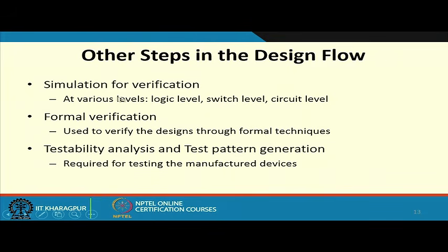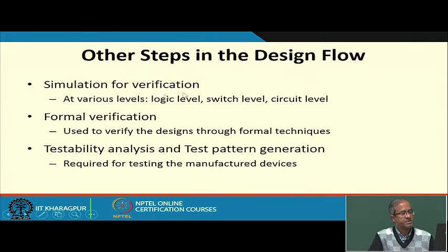So, now in addition to this, you have a few other steps also which you often carry out. For example, to check whether some step or translation is correct, you typically carry out simulation. Simulation can be carried out at various levels like logic level, switch level or circuit level. Formal verification is also a very important tool to verify the correctness of designs, and of course, testability analysis and test pattern generation are also very important, because you need to test the manufactured devices.